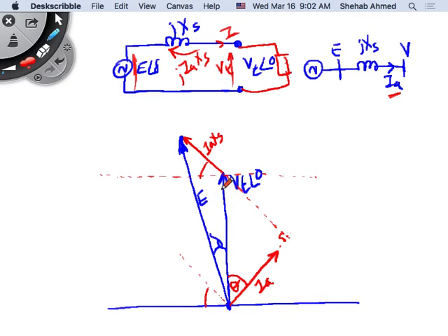So I will take this VT now and rotate it by 90 degrees. So this red waveform and this red waveform should be in phase, right? If I take this VT and this IA and just rotate by 90 degrees, I drew this 90 degrees from this, right? So that means that VT and this phasor here will be superimposed on this parallel line, this horizontal line, and this angle will be theta. Is everybody okay with this?